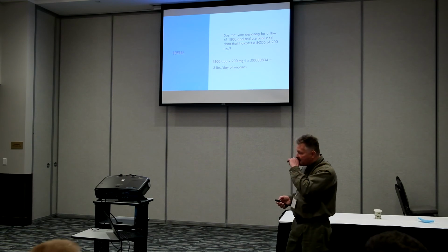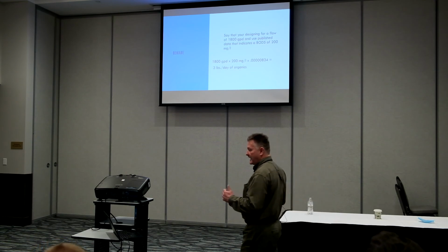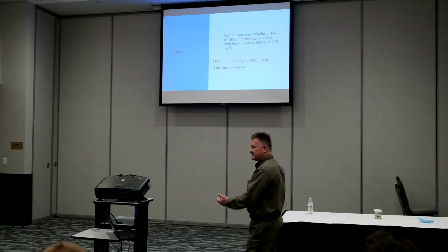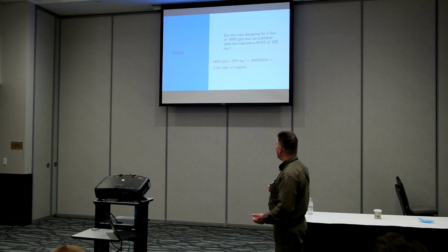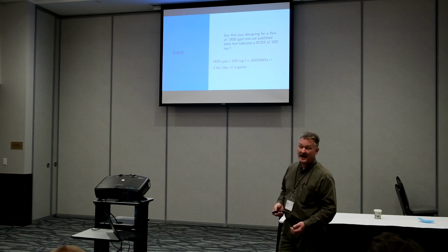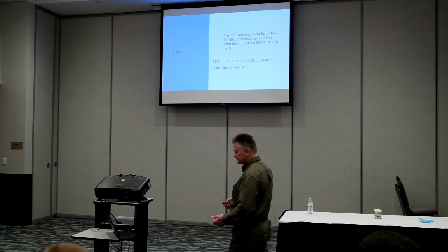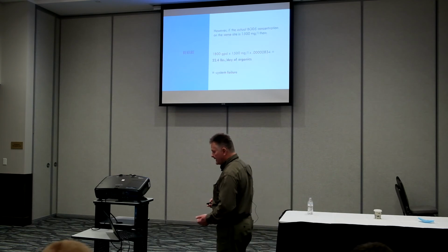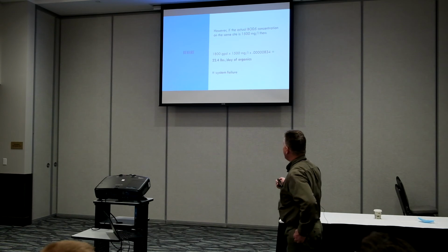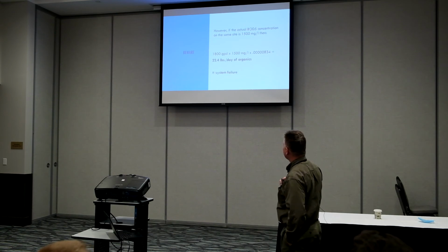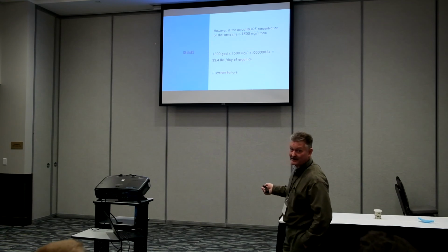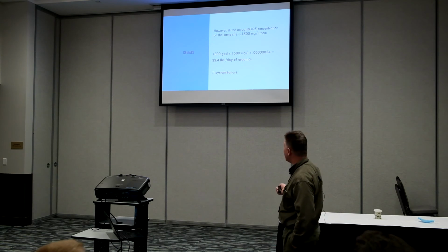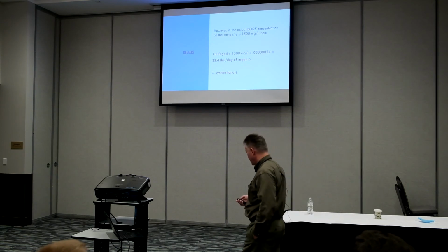Now we have to beware. Say you have a design of 1,800 gallons a day, you look at the reference manual and it states that the waste stream should be 200 milligrams per liter. So we design that, plug it in a calculation, get 3 pounds of organics, so pretty easy to deal with. But beware that if we actually have 1,500 gallons coming into that 1,800 gallon design, we now have to deal with 22 pounds of organics that system has to rely on. So what's that going to result in? It's going to result in a failure.